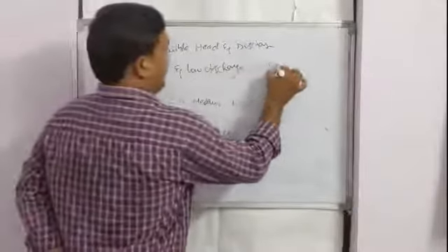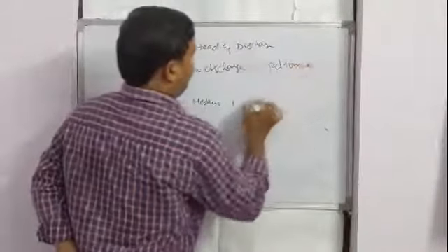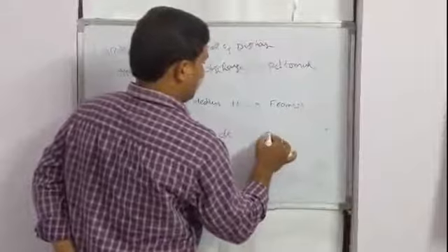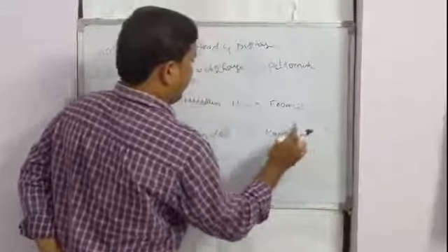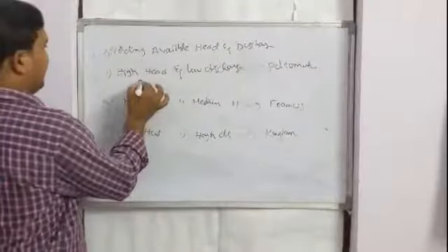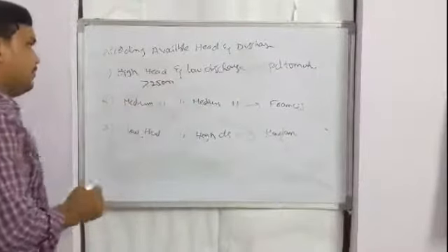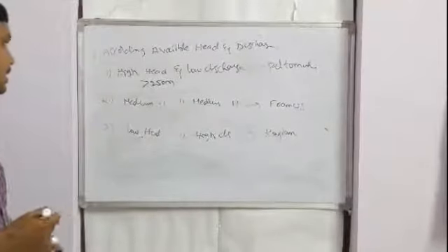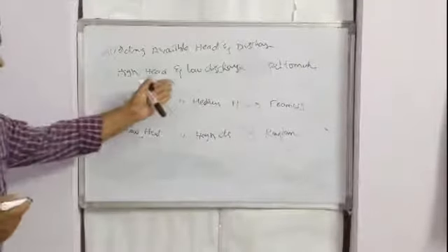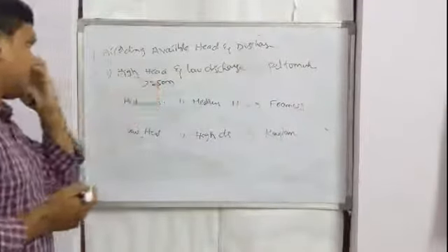This is an example of Pelton wheel, this is an example for Francis, and this is an example of Kaplan. So for the high head turbine, Pelton wheels generally require greater than 250 meters of head, meaning the head from the reservoir to the center line of the nozzle is greater than 250 meters.